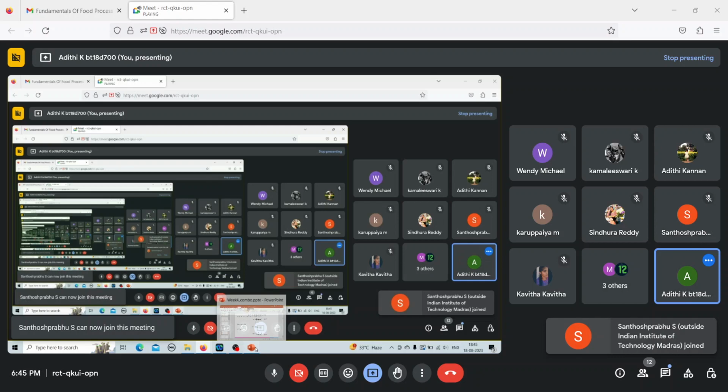So the energy balance again is S into lambda, which is the energy of the steam coming in, plus FCPF into (TF minus 273), that is the energy associated with the feed stream, equal to LCPL (T1 minus 273), which is the energy associated with the concentrated product, plus V into HV, which is the energy associated with the vapor that is coming out. So this is the total energy balance. We can calculate V from the mass balance, and we can calculate S from the energy balance.